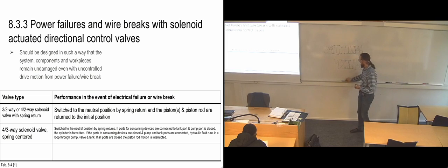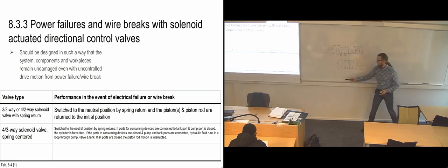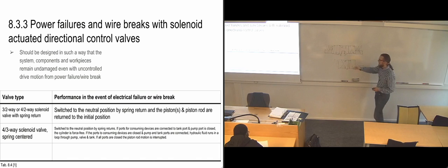So maybe it would be better to have a loop here, so that you have your pressure port returning directly to your tank. Because then you would know that this pump is just going to stay there. It's going to pump. It goes 24/7. It always delivers hydraulic energy into the system. But in this particular part of the system, if we have a power failure, we don't want to block it off, because we want the pump to continue working, because then the pump gets no resistance.